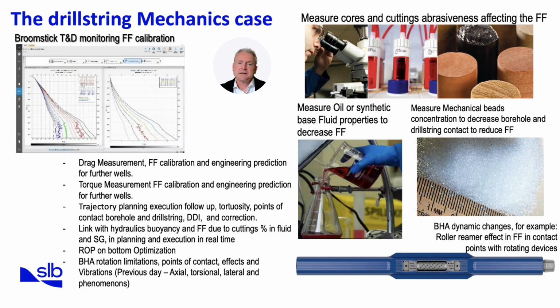Now let's look at the practical aspects of drill string mechanics monitoring. We start with drag measurement and friction factor calibration. By measuring drag during tripping operations and calibrating against modeled predictions, we can improve the accuracy of engineering forecasts for future wells. Torque measurement follows a similar process, enabling prediction of downhole behavior and mechanical loading.